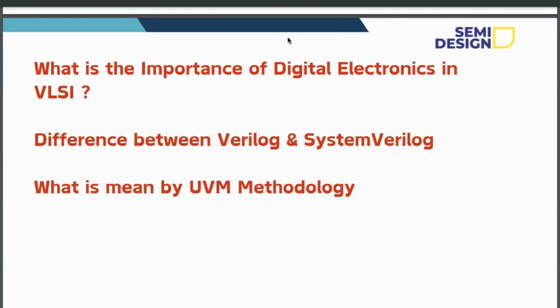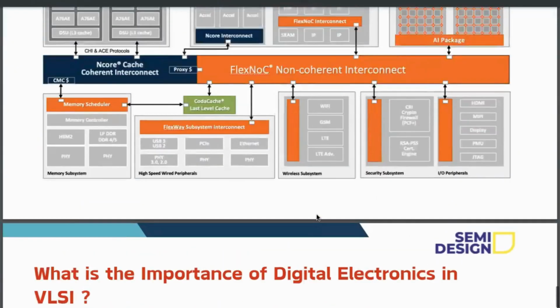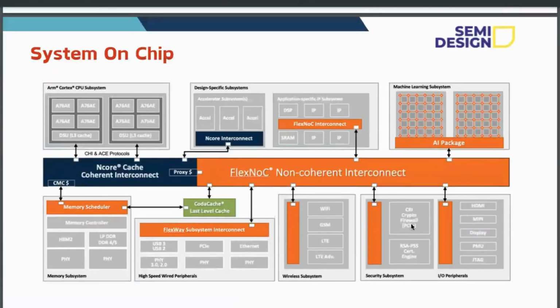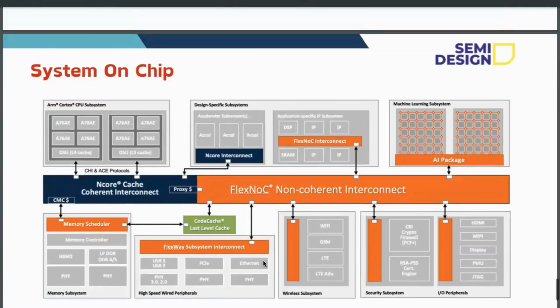The difference is, if you use SystemVerilog to verify any circuit, it will take some four or five months, as I'm telling industry-wise. But if you use UVM, you can verify it in only two months because it has all standard libraries like that. Many things are there internally. So that is the difference between Verilog, SystemVerilog, and UVM. These types of SoC level circuits we will verify using SV and UVM.